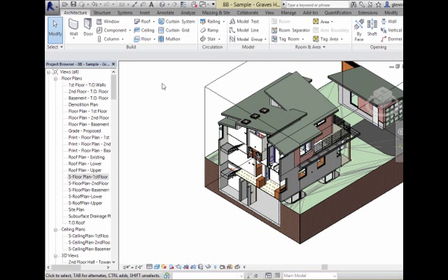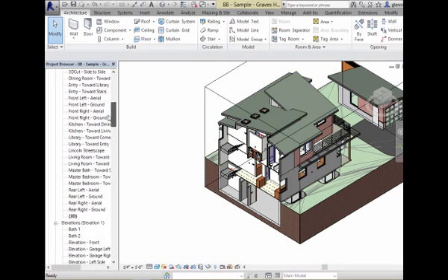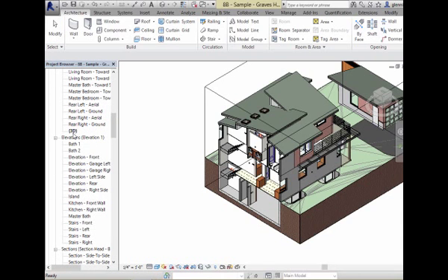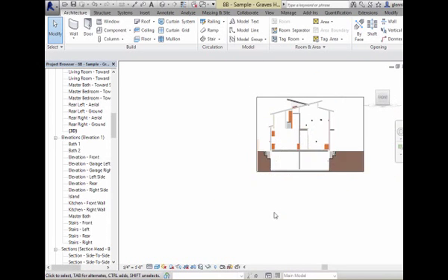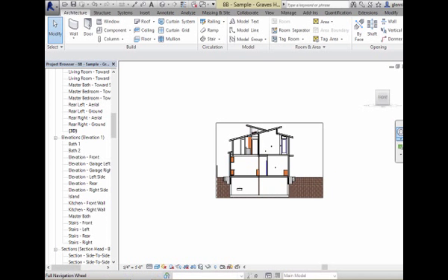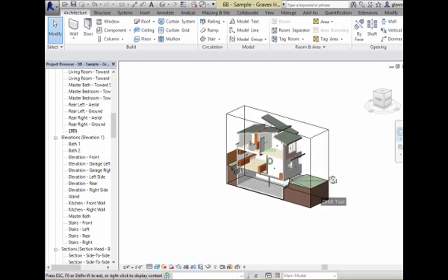Just the default 3D view is a great starting point, and I'll usually get that by either clicking on the little house up here at the top, or coming on down in the 3Ds. I have a 3D default view, the one that has little brackets on it. Once I have that, I can right-click on the view cube over there, and there's this Orient to View choice. It's a little hidden, but within there, I can then go through and choose any of these different sections. So, if I want to get a section at line 8, it moved the section cut to there.